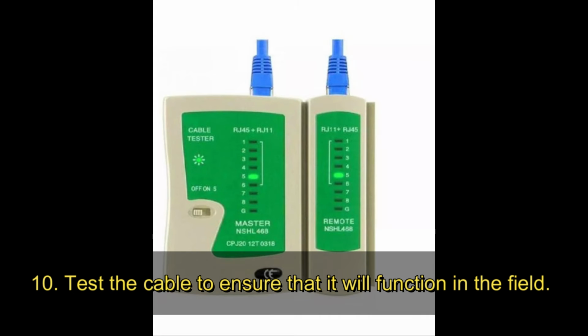Step number 10. You need to test the cable to ensure that it will function in the field. Miswired and incomplete network cables could lead to headaches down the road. In addition, with power over Ethernet making its way into the marketplace, cross-wired pairs could lead to physical damage of computers or phone system equipment, making it even more crucial that the pairs are in the correct order.